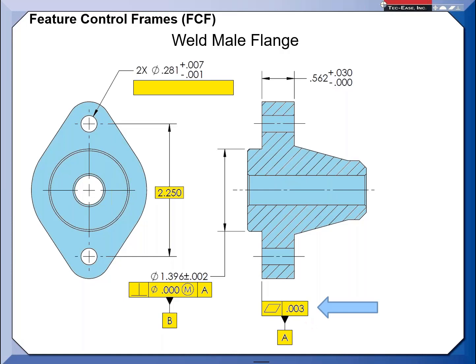Yeah, it could possibly, because when you start taking a look at this, what winds up happening is, think of it this way: if I was to bring this flange into contact with the datum simulator, or TGC, I'd hit upon the high points here. In this case, the variation would go into the part. Some people just look at this and think that the plane can just tilt this way or tilt that way within the zone. Well, your worst case could be something like this. You actually could get a crown in here and maybe get what the standard refers to as a rocker, or you can have some variation here.